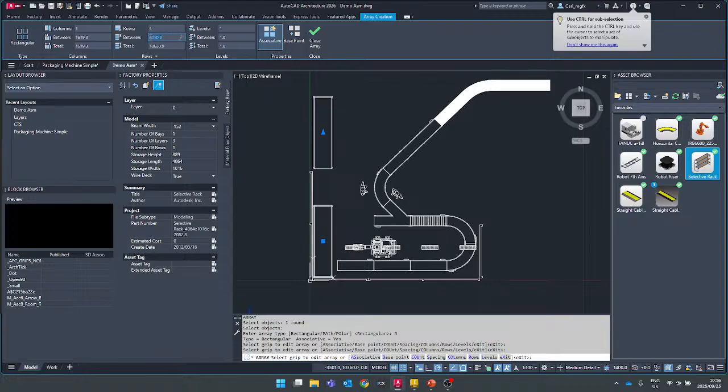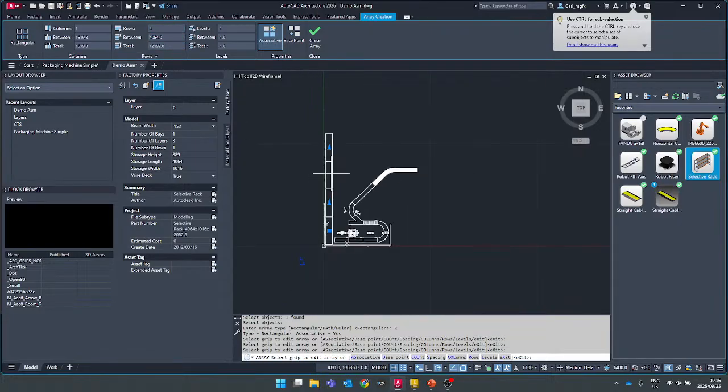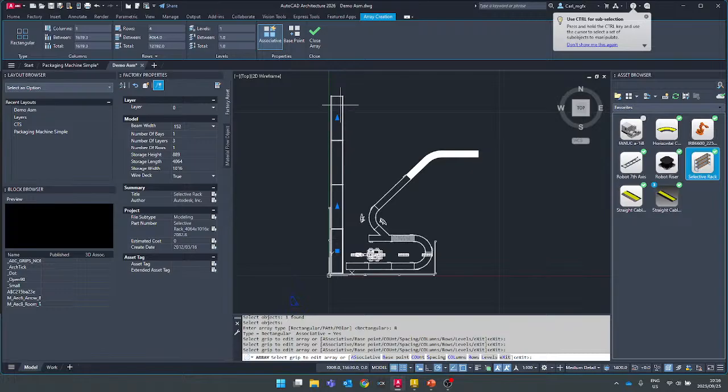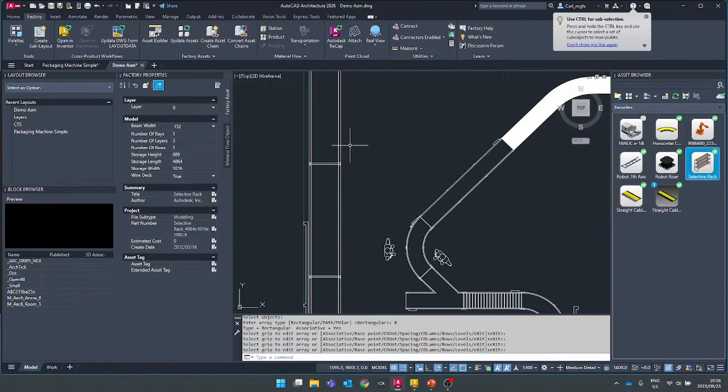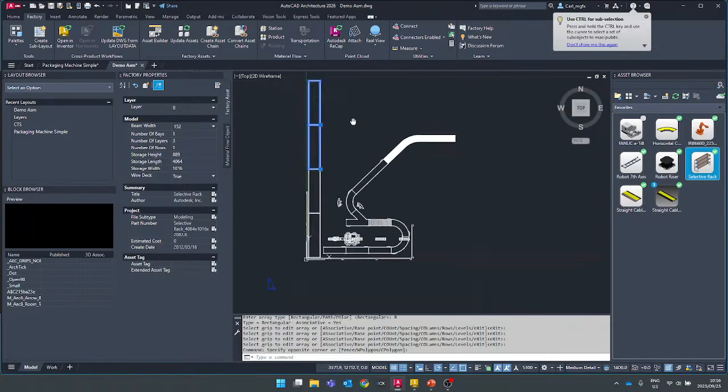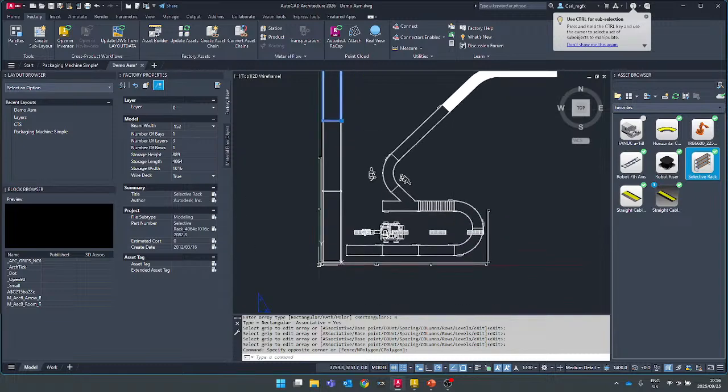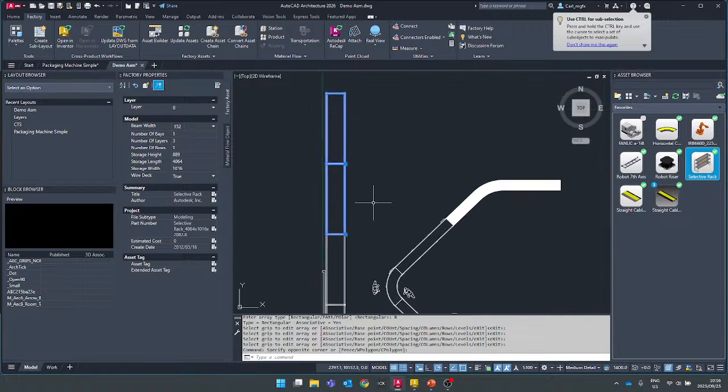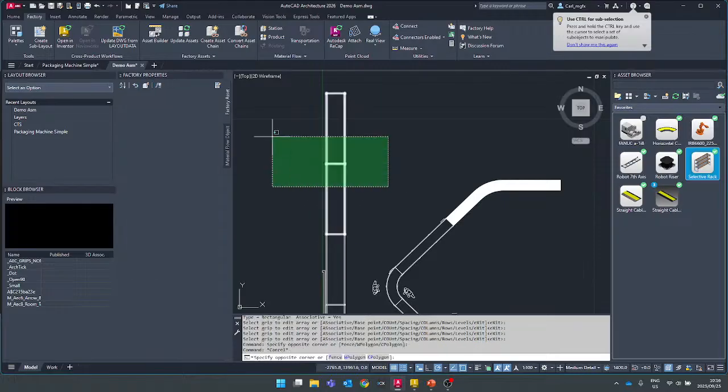So I'm going to set the between to that 4064 millimeters. and we then get that array of shelving units. And I'm going to set this off on the associativity so that it creates 4 individual blocks. Close the array. This allows, if we need to grab blocks and move them individually. You could always explode the array and achieve the same thing.